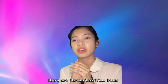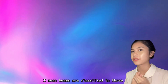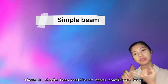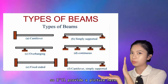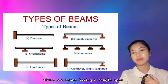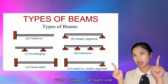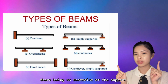There are three classifications of beams: simple beams, cantilever beams, and continuous beams. So I will provide a picture here. Simple beam. These are beams having a single span with a support at each end, there being no restraint at the supports.